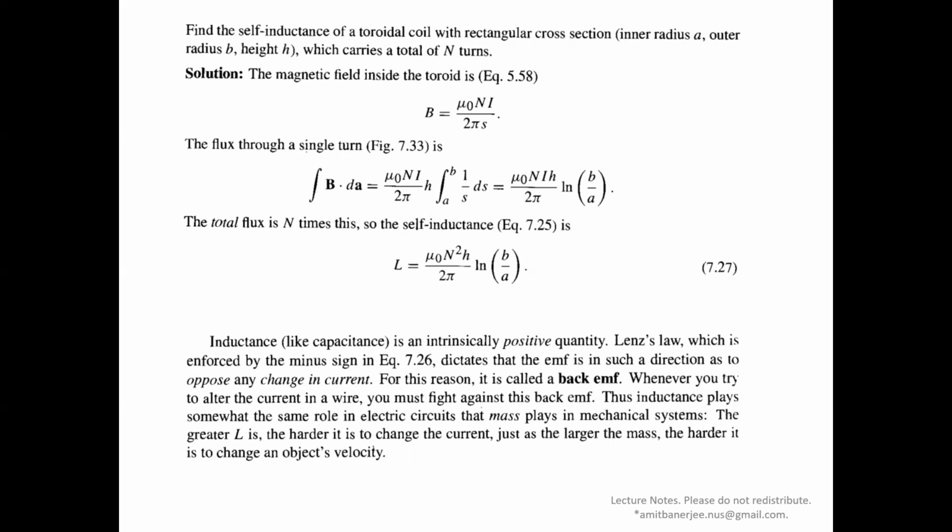Whenever you try to alter the current in the wire, you must fight against this back EMF. Thus, inductance plays somewhat the same role in an electric circuit that mass plays in a mechanical system. The greater L, the self-inductance, the harder it is to change the current, just as the larger the mass, the harder it is to change an object's velocity.